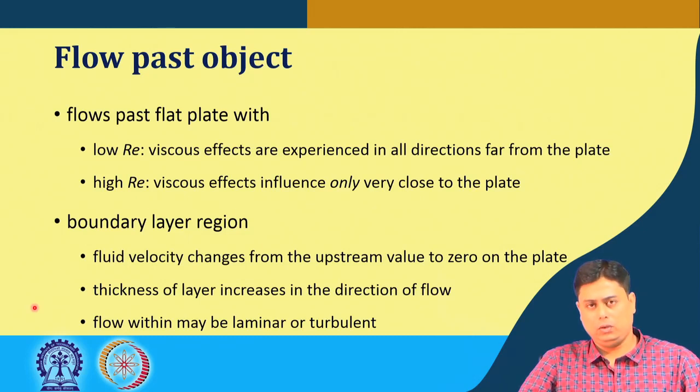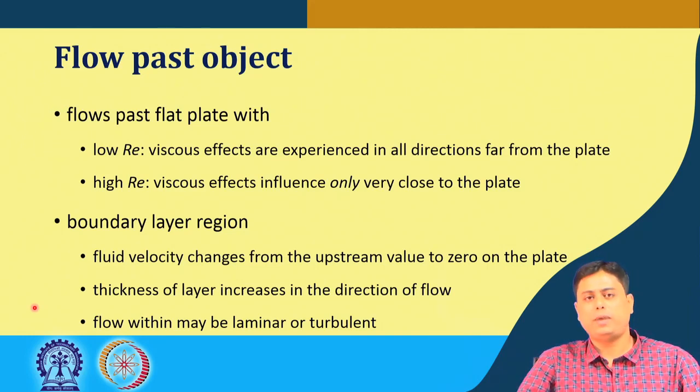the inviscid flow. When the viscosity is 0, the Reynolds number is infinite, which practically does not happen, but in such cases the thickness of the boundary layer, or the effect of this viscous force, is contained only near the wall in a very thin layer, when the Reynolds number is very high.